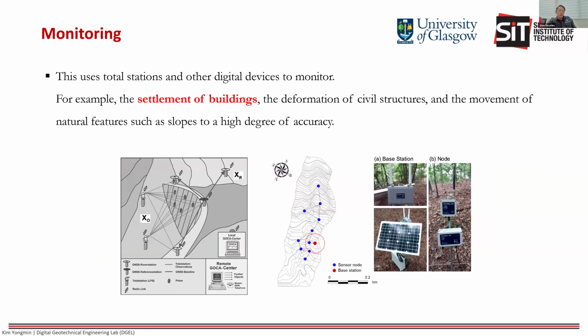After construction, monitoring ensures that the structure or terrain remains stable during the construction. You will see very common monitoring tools such as ground settlement markers, which monitor the deformation or settlement of the surrounding structures during construction. So it's important to track displacement, settlement, and deformation as a civil engineer, because you want to know that the work that you do has minimal impact to the surrounding structures, especially in an urban built-up area like Singapore.